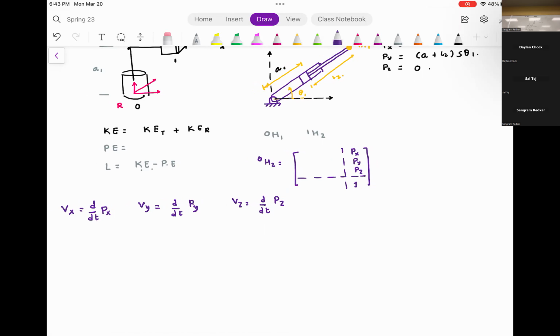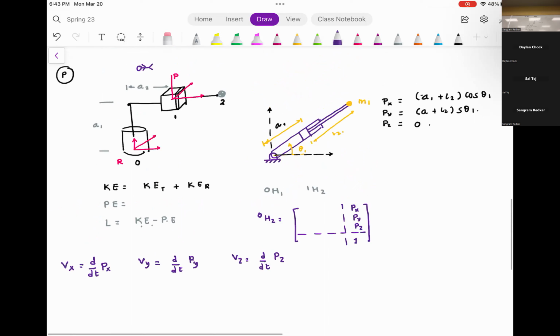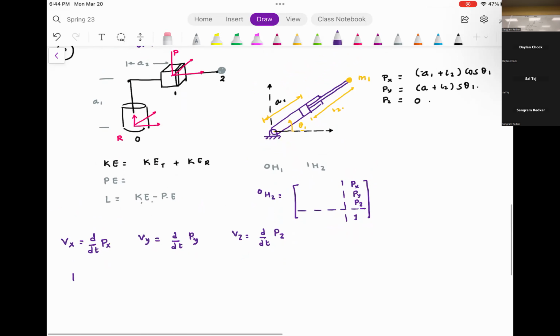Yes, and with forward kinematics, what I did here is I took the shortcut, because I believe that this problem we already solved. So we have the solution, but the step is we have to do the forward kinematics, get the values of Px, Py, Pz, find Vx, Vy, Vz, and then find the kinetic energy as 1/2 m2 (Vx square plus Vy square plus Vz square).